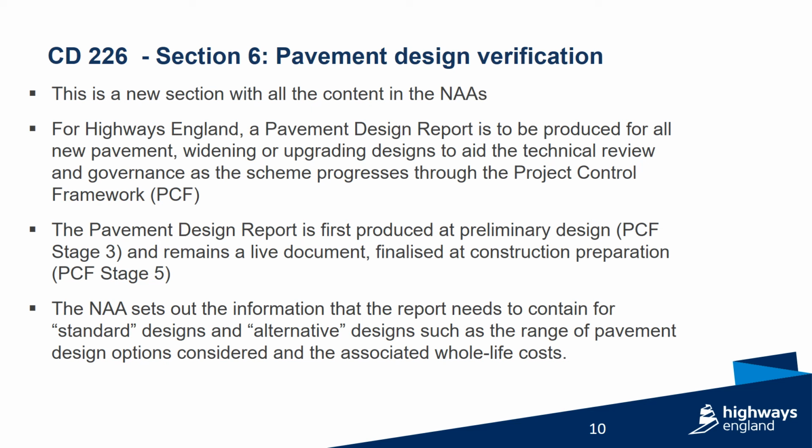The pavement design report is first produced at preliminary design stage, PCF stage 3, and remains a live document and finalised at construction preparation, PCF stage 5. The National Application Annex sets out the information that the report needs to contain for standard designs and alternative designs, such as the range of pavement design options considered and their associated whole life costs.